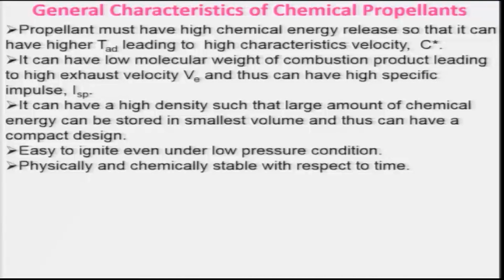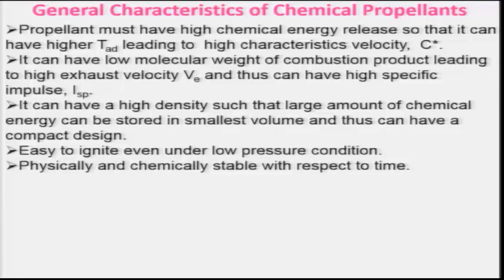And the propellant must be physically and chemically stable with respect to time, otherwise it will not be of much use. Suppose you have stored the solid propellant which will be used in a missile, and it has deteriorated and been physically or chemically damaged. Then naturally when it is fired it will not perform well, and your mission will be a failure. So one has to keep this in mind: generally the solid propellant is kept for years together.